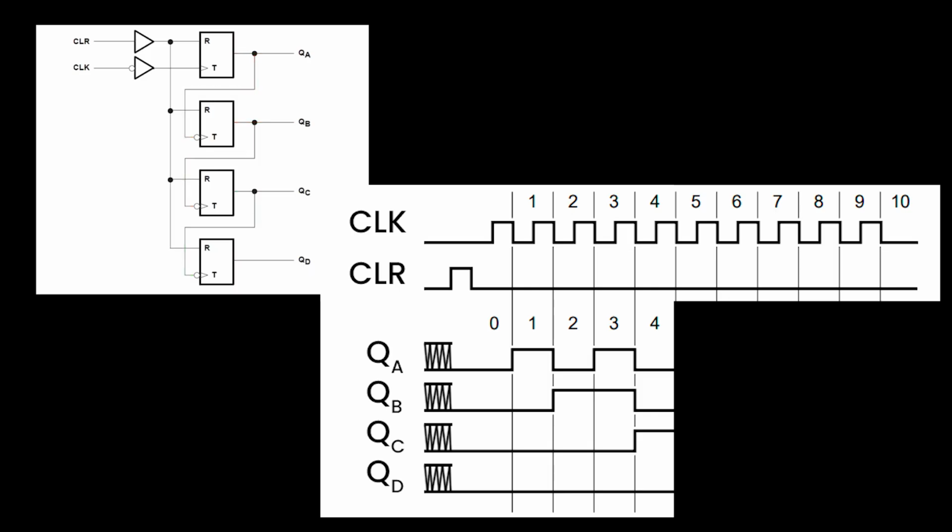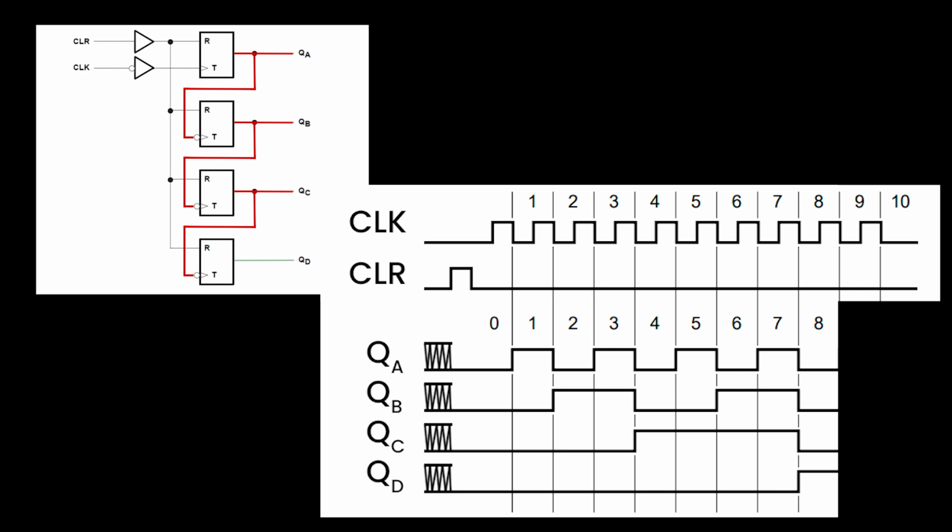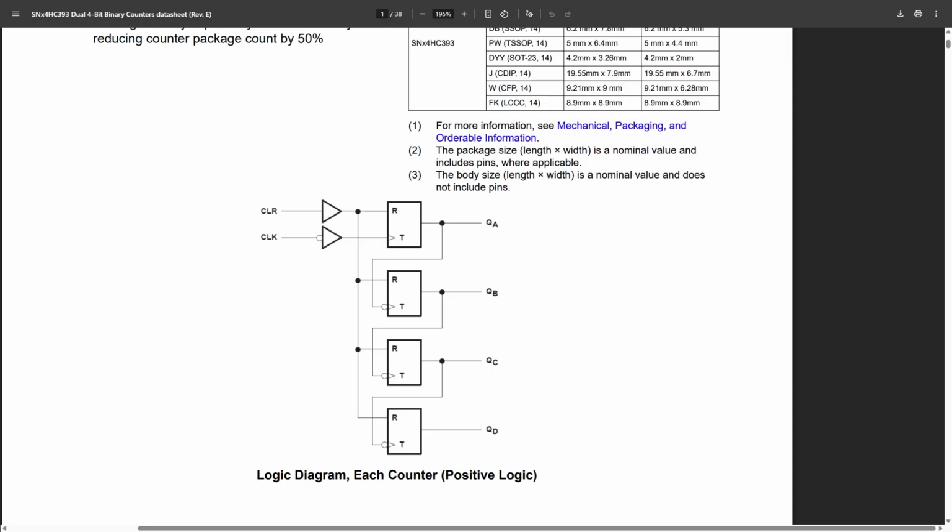I guess you already know what's going to happen. After 8 cycles, QC gets set to 0 and toggles QD. Another 8 cycles later, QD would fall back to 0, and this would set us again on the initial state of the simulation. What would happen if the output QD was connected to another T flip-flop?